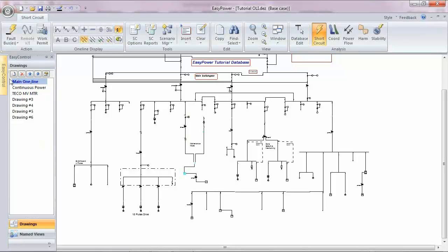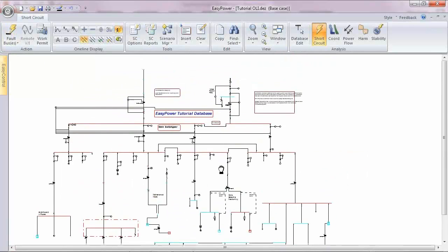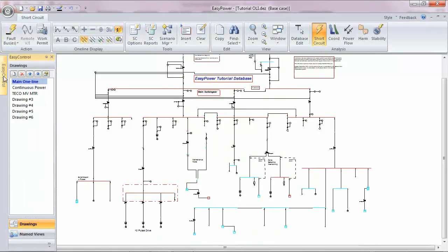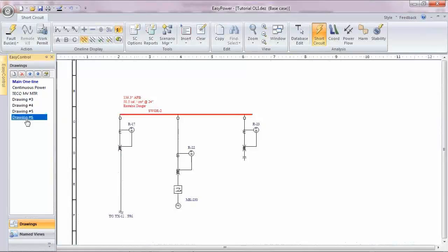And so if you only are in one drawing and you perform an arc flash analysis, what you're going to see is just those items selected. Now if you perform the fault analysis out here, you see all the results, and those are going to be displayed in all of our images as well, or all of our drawings. So keep that in mind. But like I said, I think personally it's better to keep the results, maybe depending on the application. So it's really relative.